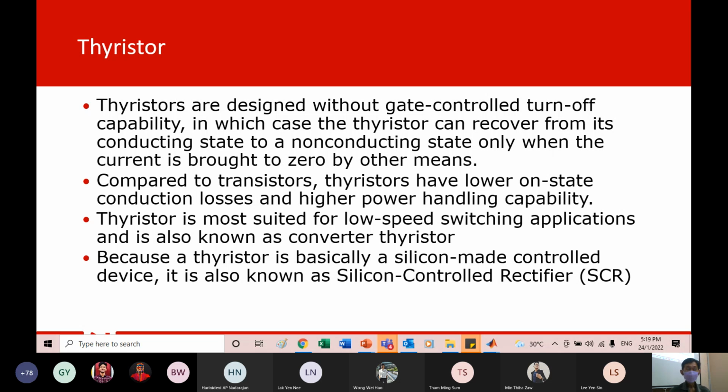So it works at a very low frequency, so all those switching losses that only appear on the nanosecond scale won't really affect this thyristor, because it works at a very low frequency. So you have to be very clear when you talk about thyristor. It always has something to do with AC circuits at low frequency. And of course, it has very high power and current.